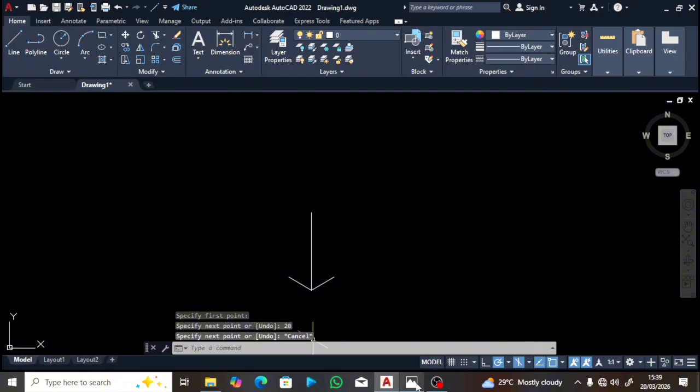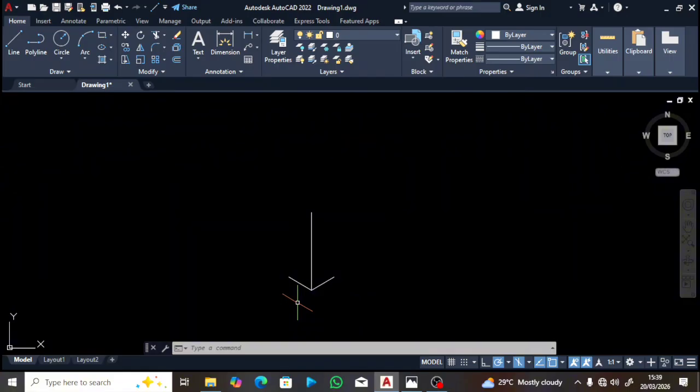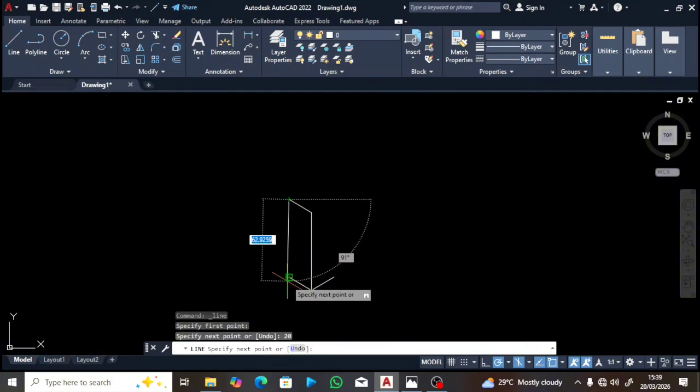All right, let's come here again. From the drawing, I went like this, went like this. So I will need to come from here to here. It's still the same thing as 20 millimeter, the same as this measurement. Then come down, join them together. So I'll click enter instead of picking the line, because it's the line. Click enter on your keyboard, or you can come here to pick the line command. From that point, it's showing 150, as I've said. It's still the same thing as 30 degree from the left. Okay, so I'll go by 20 millimeter, type 20, click enter, then join it with this one. You can see that it's showing green line, right?